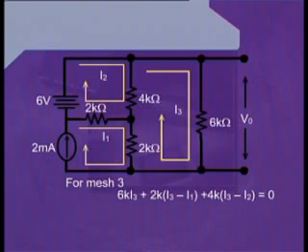After reaching the 4 kilo ohm value, once again, we have written I3 minus I2, and this is also due to the reason that the currents I3 and I2 from that branch are flowing in the opposite direction to each other. Hence, we must take the difference of these two currents.